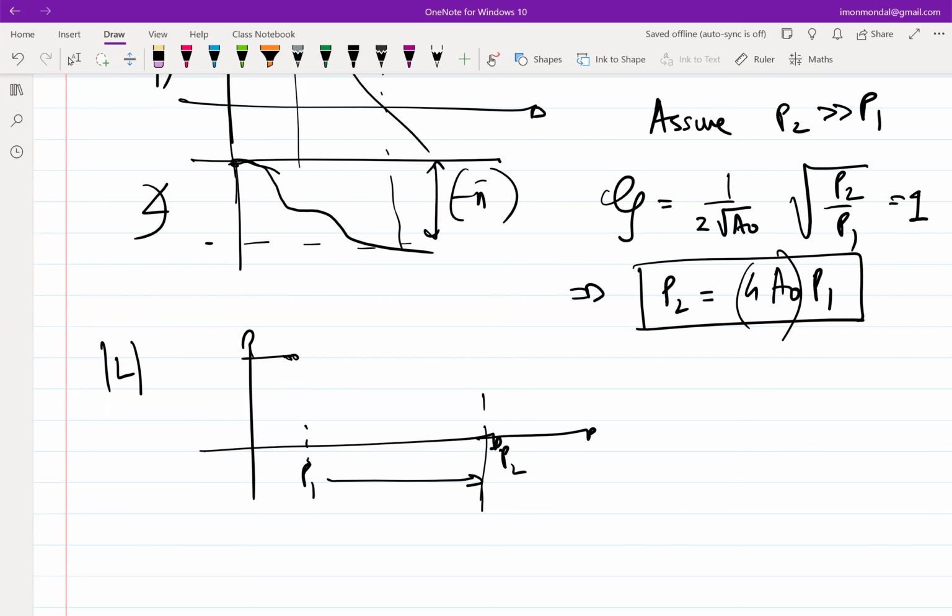So now the natural thing to ask is, since everything is dependent on where the location of UGB is with regards to how fast the system will settle, and whether the system will actually be stable or not, we need to also figure out where is the omega u or the omega UGB or the gain crossover frequency of a second order transfer function, right? So if I have to find the gain crossover frequency, I understand that this is of this format, A0 by 1 plus S by P1, 1 plus S by P2.